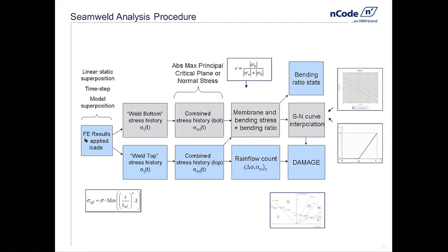That's with this release. This methodology actually gives us avenues into doing the exact calculations out of the pressure vessel code, or using it for other techniques as well. But in the version 9 implementation, we're taking the linearized stresses from solids and using them along the same path that we've used for the shells.